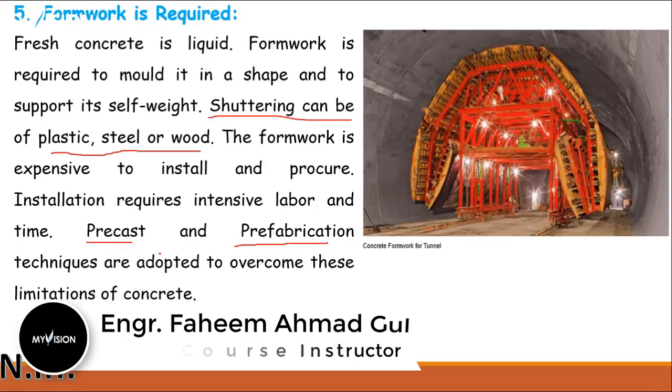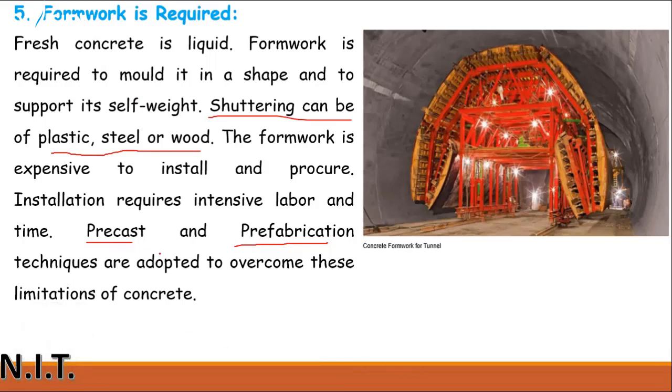Precast and prefabrication is a technique which is used for that type of structures which we cannot construct on the site. We have to construct the structural element somewhere else, and then we bring those structural elements to the site and combine them together. As you can see, this technique is used in bridges.